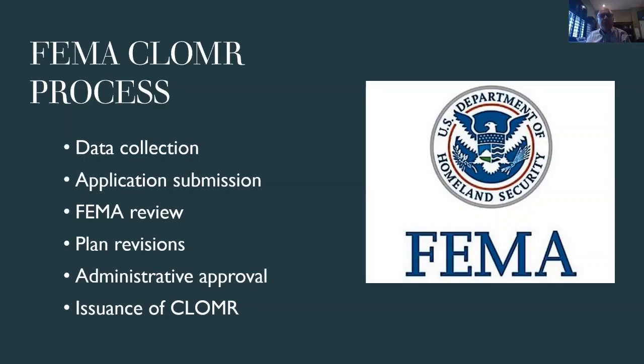Well, let's start with CLOMR. What is CLOMR? As Ron said, conditional letter of map revision. FEMA established a processing procedure back in 1986 that basically helps the communities, developers, and applicants if they want their engineering analysis reviewed before the project is completed.